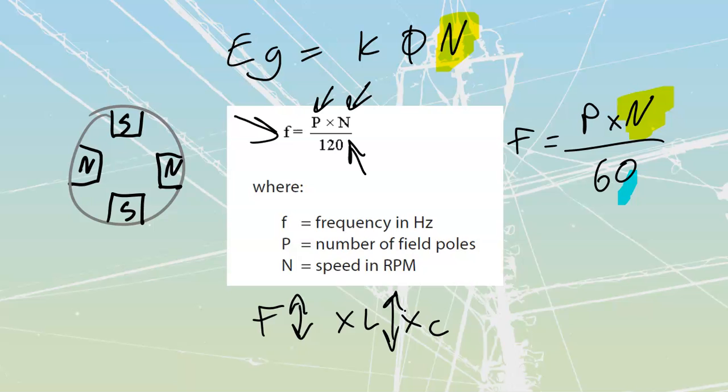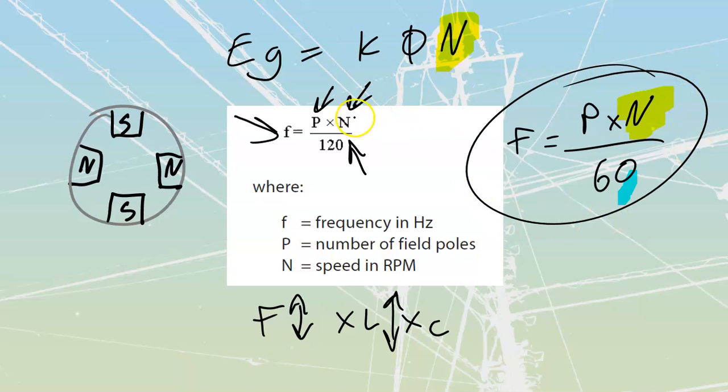The other thing that we have 60 hertz for is it is a really easy system for us to deal with a lot of our timing. Things like computers and data that's going to be put out in specific little bursts. We need to make sure that data is able to be picked up and read by other things that have the same sort of timing. So we just don't want to screw around with the frequency. Therefore, we're not going to screw around a lot with the speed of our alternators.